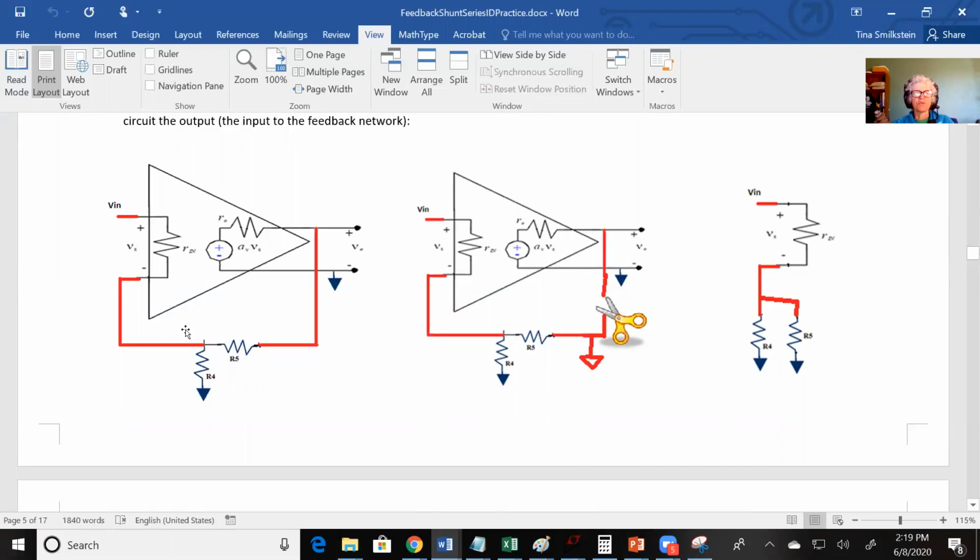When you do this, you get to treat this amplifier as another two-port problem. So remember when you were finding R out, you zeroed V in, or if you were trying to find GM of an amplifier, you zeroed V out. You get to use those same rules when working with this, because it does have gain.